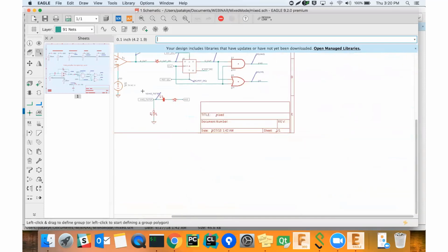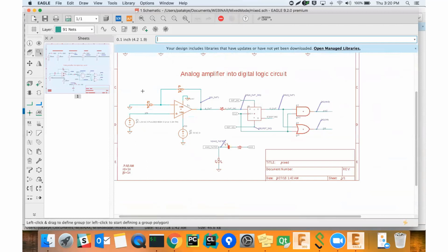So I'm going to recap a little bit. We went through analog simulations, and simulation in general with Eagle. We started with analog simulations, and we went through a bunch of examples. Some using SPICE model files, subcircuit files. Some using model cards like the diode that we looked at. Some components that didn't require any model files at all. But we simulated successfully transient simulations, simulations over frequency.